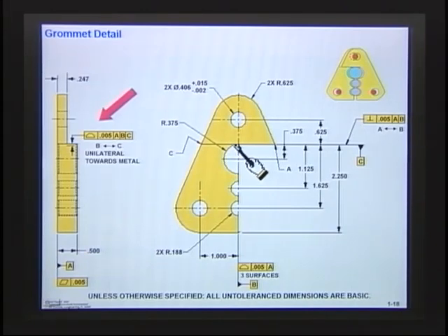And the only other alternative I would have had to do is I would have had to show this line 2.5 thousandths down below this line, and you wouldn't have been able to see it for training purposes. So I thought for training purposes I'm just going to use a unilateral, and it's another tool in our toolbox, and there's some cases you use it, so that surface is down. And then underneath here I said that that was between B and C. There's my point B, there's my point C, and that unilateral tolerance applies here. And that was 5 thousandths. The mating part would have 5 thousandths. That gives me my gap of 10 there again.